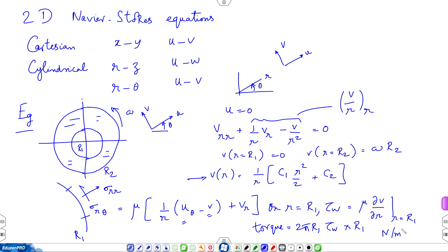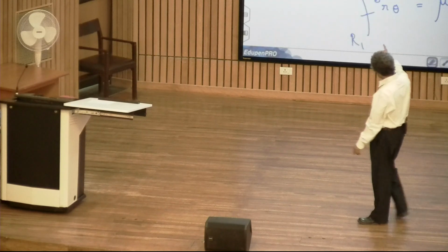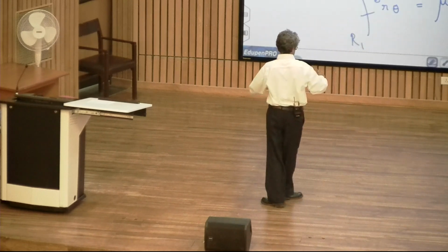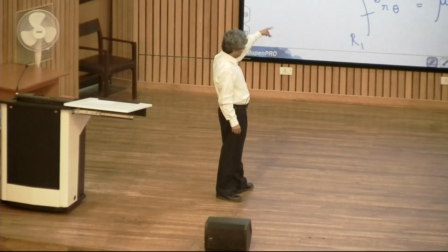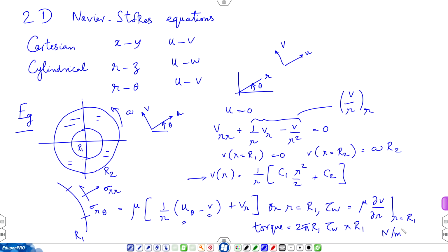Now, in problems that you will be given, as well as problems given in the book, viscosity is prescribed to you, viscosity is given. But if you deal with a new medium, the question is, what is viscosity? So, this approach is often used to find viscosity. You have concentric cylinders, and then you find the moment acting on the inner cylinder by suspending it with a torsion wire.